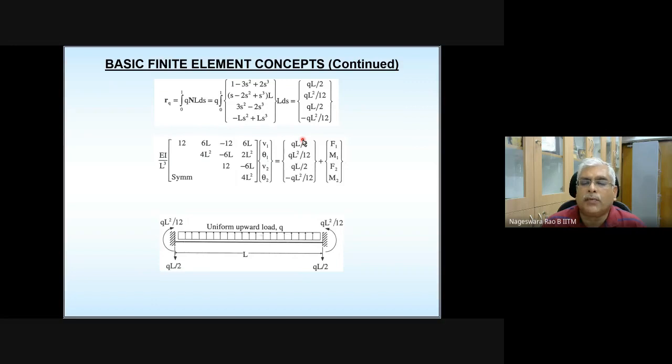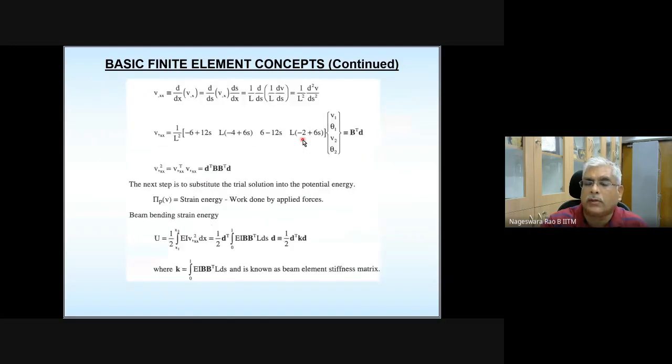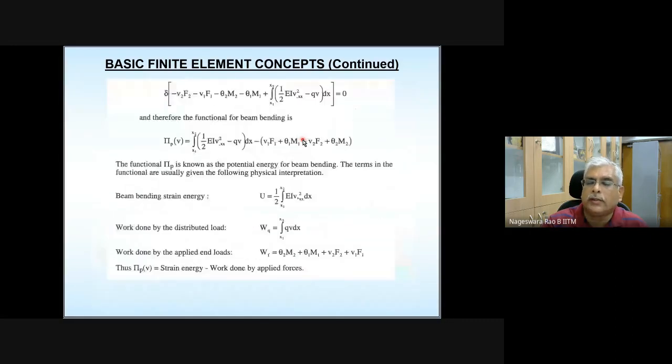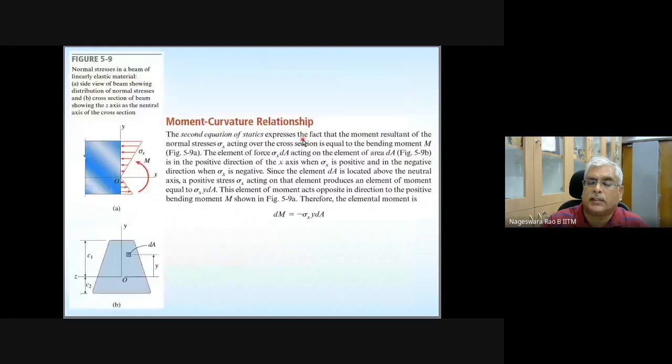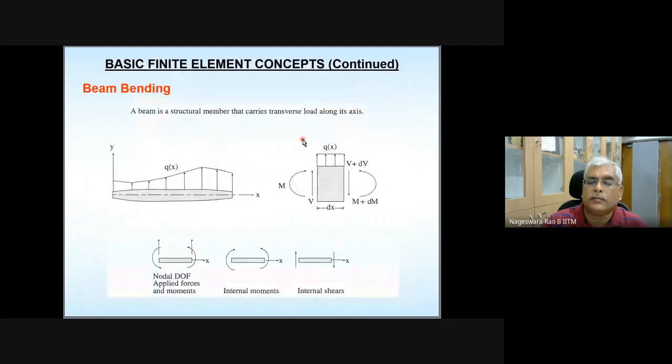Sign conventions for what? That's why I told you in the beginning, you need to make a note of this sign convention. This is the sign convention for nodal degrees of freedom, applied forces and moments, and this is for internal moments and internal shear.